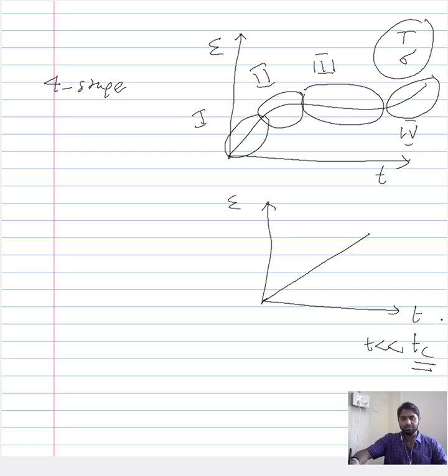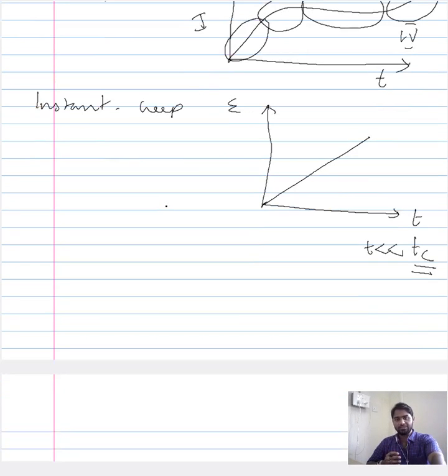So when you consider this t here with respect to the overall time during which the creep test is being done, this time is relatively small. So what we are talking about here is instantaneous creep, and we want to understand what material behaviors are responsible for it. Now since we have a fair clue of what happens when you impose a load on a material, we can relate that to this stage of the creep and see what factors are responsible for it.